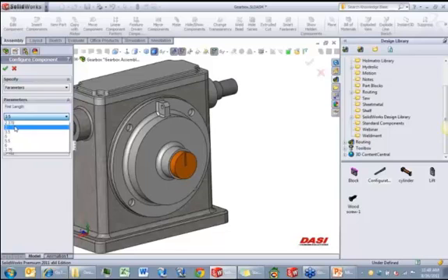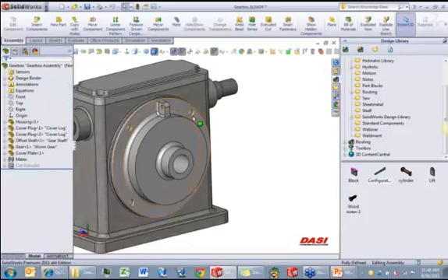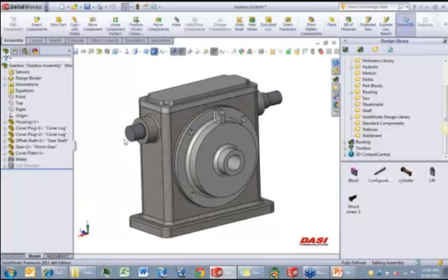Sometimes if you pick a length like this 2-inch one, well, there's other second length options that are available, okay? But only these 3 based on the first dimension that I chose. Or maybe this one right here, the 4-inch, has an option to turn off the slot. And see, then you can see the slot go away. So based on your selection from this tree, it's going to give you more selections. It's intuitive that way. So keep in mind using the configuration publisher for dragging and dropping in components that have multiple configurations.